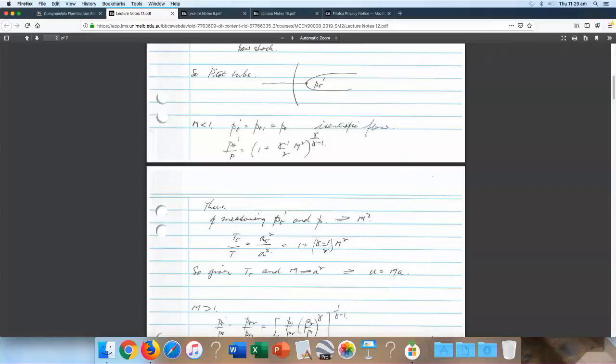If I write the equations for a shock wave, a discontinuity, I got the shock Hugoniot, or the shock adiabat, and that gave me the connection between the pressures across it and the density across it. Everything else I want to know about the flow upstream and downstream of a normal shock. And I used that normal shock relationship finally to get what I have for an oblique shock.